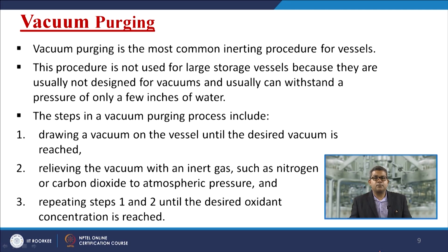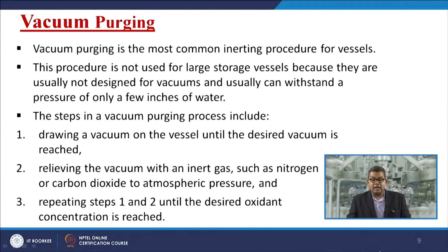So, let's have a look at vacuum purging. Now, vacuum purging is one of the most common inerting procedures for vessels. It's quite simple. The only thing is that it's highly energy intensive. This procedure is not used for large storage vessels, because they are usually not designed for vacuum and can usually withstand a pressure of only a few inches of water.